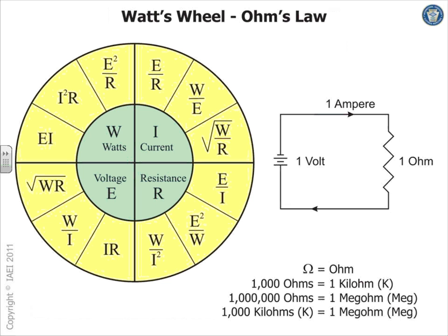I'm going to move through these, guys. This just talks about why we care about grounding and bonding. When I teach electrical, I always summarize: in order for electrical power to work, all you need is one hot on a grounded system and Mother Earth at the end. So take 120 to your backyard with one wire, tie that wire to one end of a bulb with a socket, and tie the other end to a ground, like any metal object stuck in the ground. In Minnesota at this time, you will probably get full brightness out of that bulb. Anybody tried that one? You're basically using Mother Earth as the return. That's no problem. The system will work.